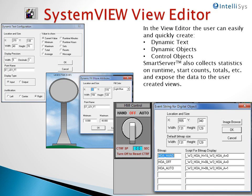In the next little panel here, we look at the dynamic fill for an ellipse. Here you can see you can scale the filling of a tank, an elevated storage tank in this case. And then lastly, we show an event string for a digital output object, which in this particular case is a hand-off-auto switch, where we're triggering 2 bits in the PLC with any control function.